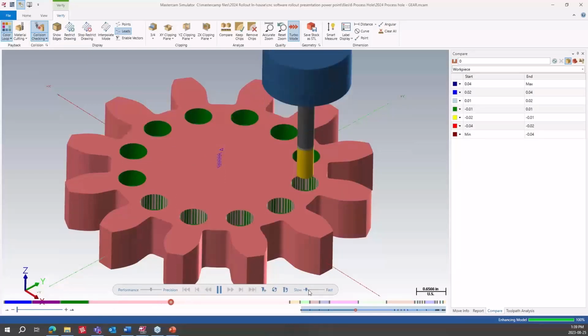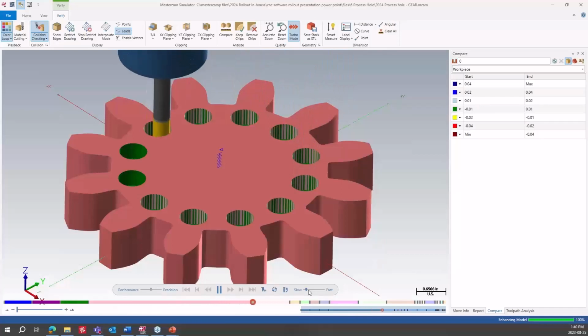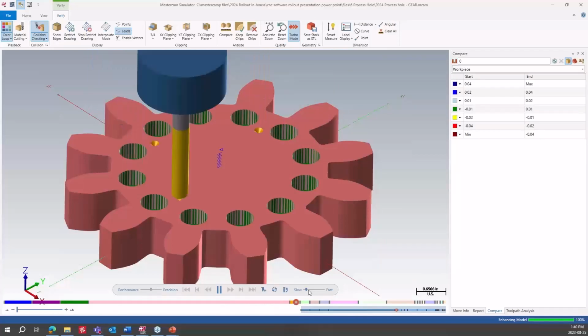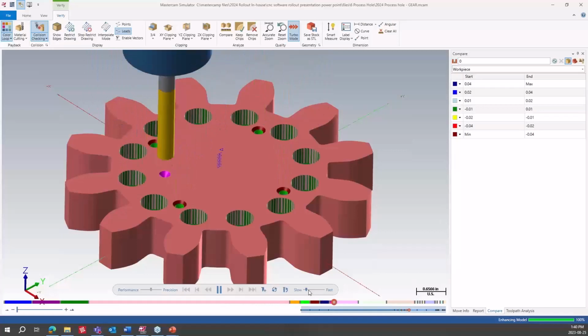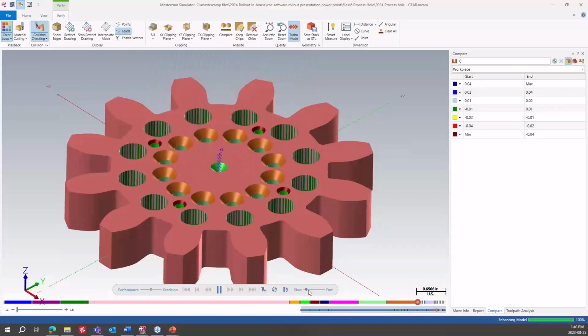So again, I've plunged. This is your helix now. So it gives you the 2 options. And then, like I say, you can delete off whatever one you don't want, kind of deal. And then center drill, and the tapping. And then same here. In my process hole library for the tapping, I've done a Z0 on it just to be on the safe side. And then again, you can change that in the toolpath itself.